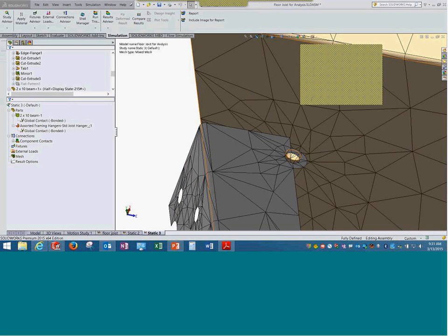Okay, looks like some question. When it comes to sheet metal, will the simulation automatically mesh it with shell elements with the center offset? Yes, you are right. So typically for sheet metal, by default, the surface is created at the center of the sheet metal part.